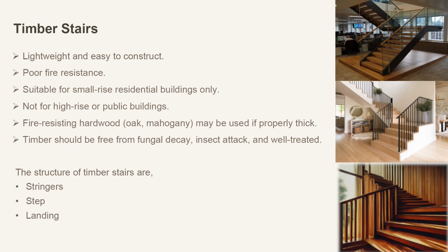Sometimes, to improve the fire resistance, hard woods like oak or mahogany are provided because they have proper thickness. And you should make sure the timber that is used in stair construction should be free from fungal decay and insect attacks, and it should be well treated before use to ensure its safety.